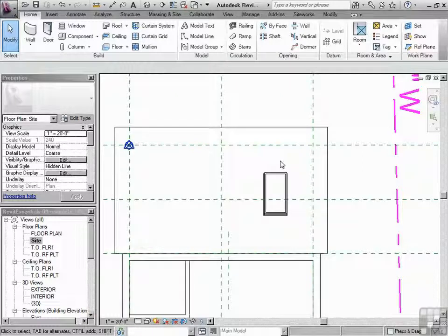And then we can just do some math where we can add up the two skylights. So that's 24 plus 24, that's 48 or 4 feet. And then we subtract that from the total. That brings us down to 13 feet. And then we would divide that by 3 spaces. So that's the space left over that we're dividing by 3 spaces. And that works out to 52 inches. And how did I get that? Well, just use the calculator and figured it out.